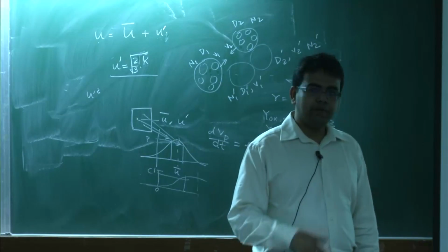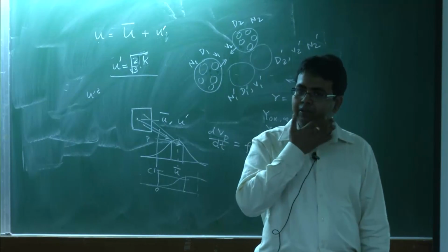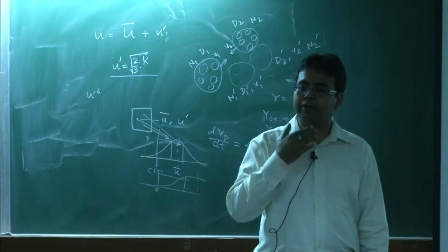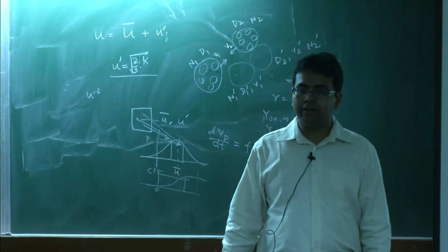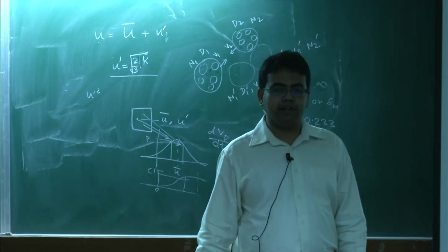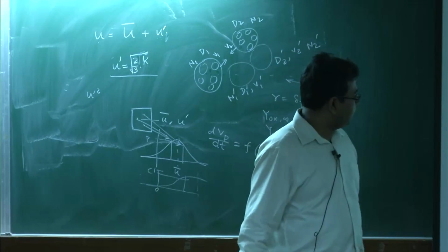Okay. So, but it will be conserved instantaneously. Then from the instantaneous mixture fraction equation, we can average it, that is the phase averaging, and we can try to get the mean and variance of the mixture fraction. Okay. These are the transport equations of the mean and variance of the mixture fraction.